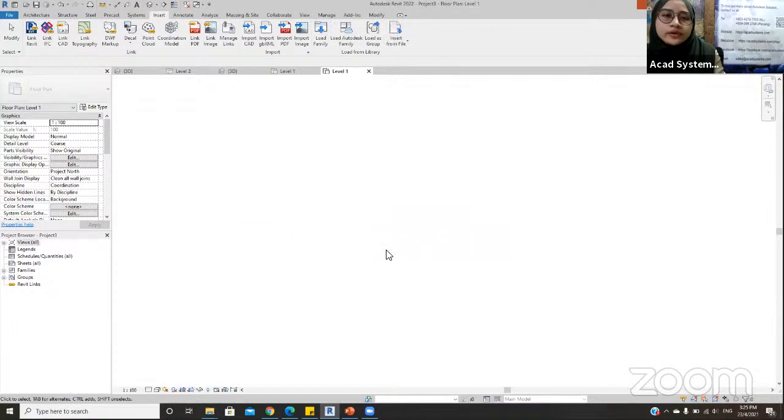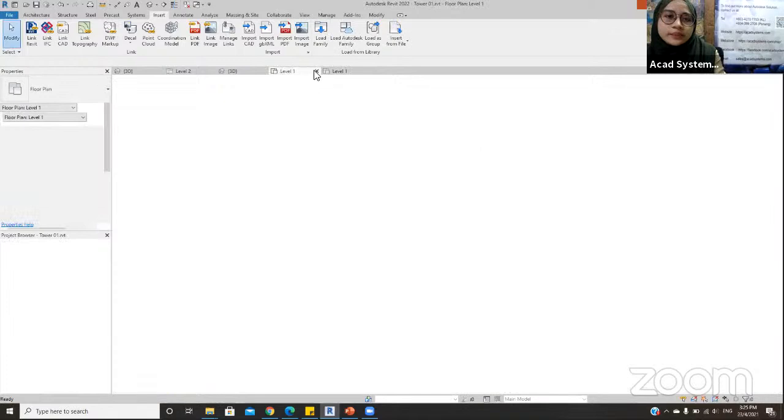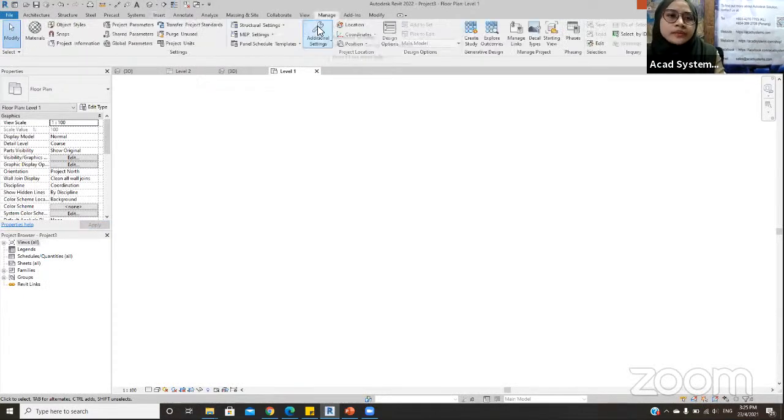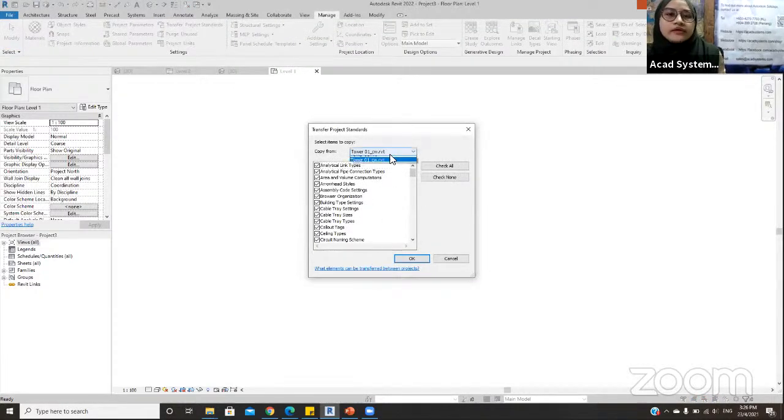And then whenever you have the next project that requires the same material, the same family, what you want to do is go to Manage, and then you can transfer the project standard. So let me go to Transfer Project Standard. Over here, you have the option of the project that is currently open. The rule is that you need to open first any project that you want to transfer, and then you can select from here. All right, so let me copy from the tower that I just made.